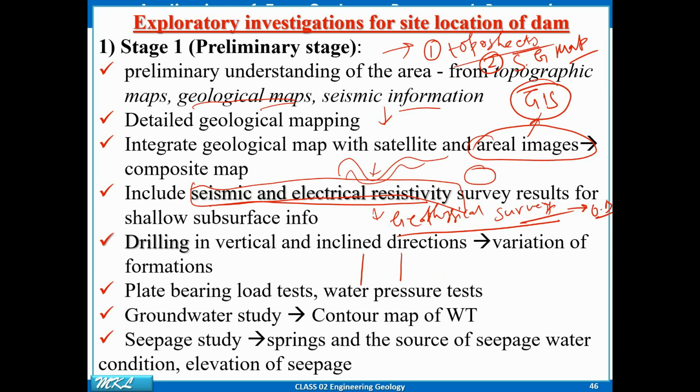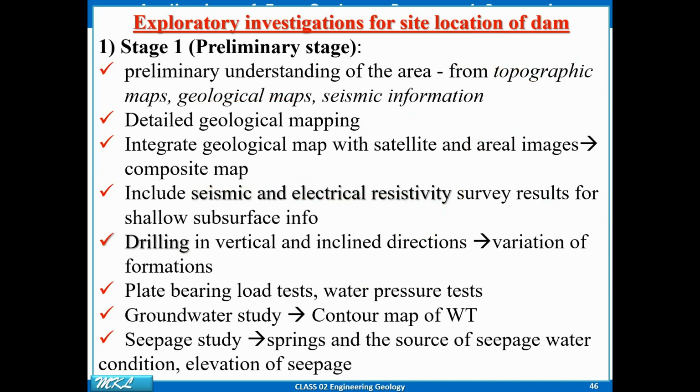If you are not getting the subsurface information from the geophysical survey, then you will be doing some drilling, normal geological drilling or geophysical logging. By drilling you can identify the formations: how many layers there are, what formations there are, and at what depth the bedrock actually is. It is an invasive technique, and by doing it you can identify the variation of the formations.